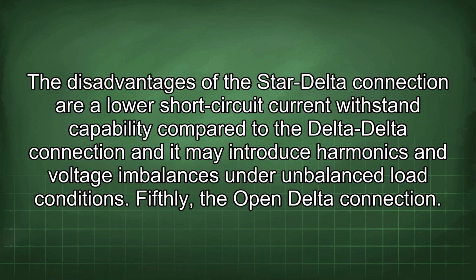The disadvantages of the star-delta connection are a lower short-circuit current withstand capability compared to the delta-delta connection, and it may introduce harmonics and voltage imbalances under unbalanced load conditions.